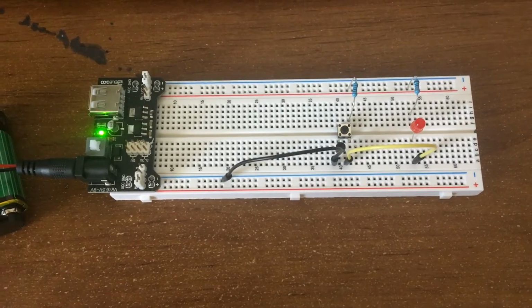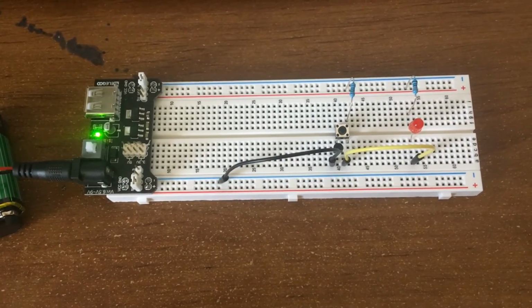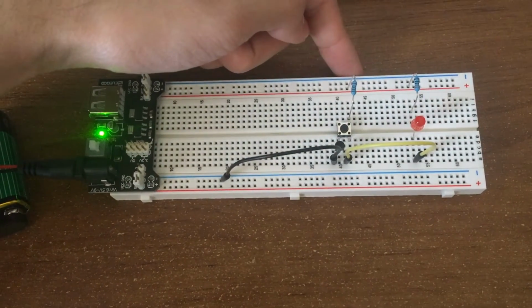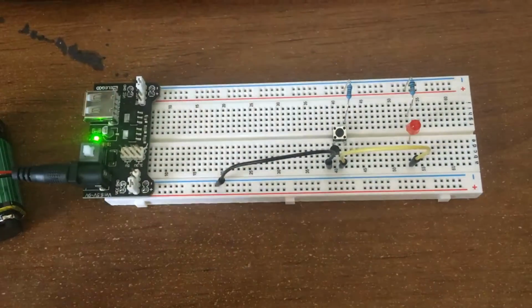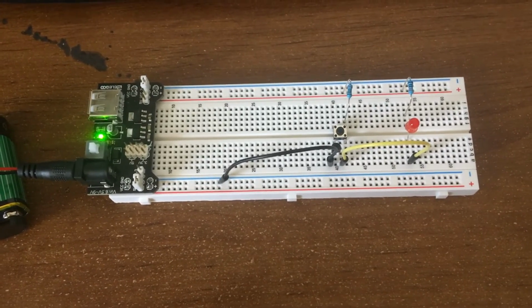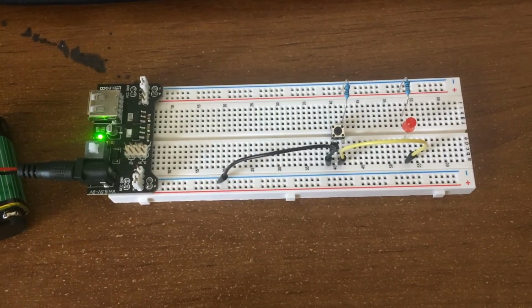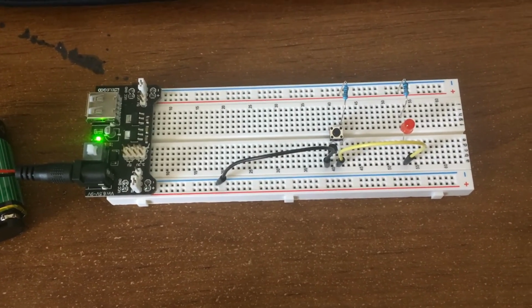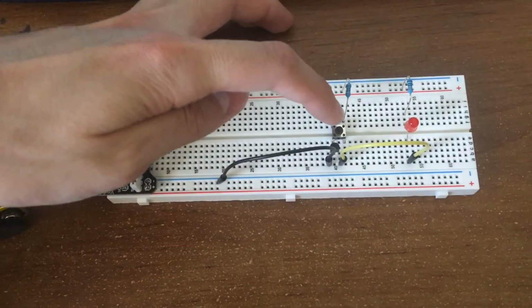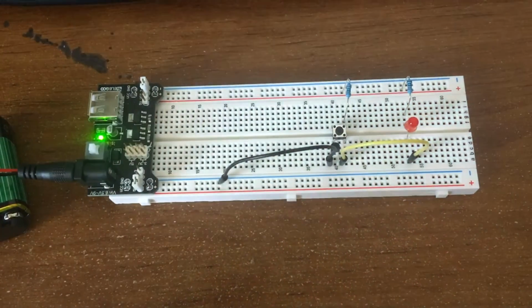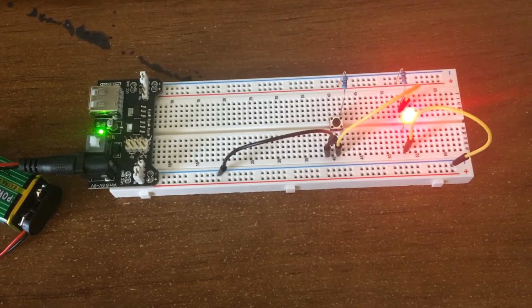Now we're going to test our first logic gate, the buffer logic gate. Our truth table says that there's only one input, which is A, and one output, which is C. Our first case, it's when both A and C are 0, meaning that if I don't press anything, the LED should be off, which it is. And our second case, it's when both A and C are 1, meaning that if I press A, the LED should be turning on, which it is.